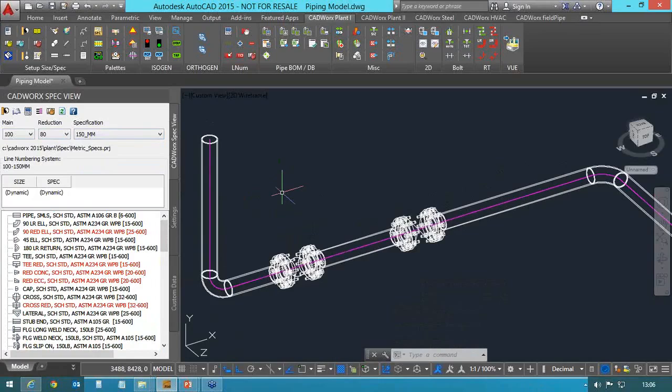Once you select this to place, you have the options of using point distance, or the component distance, or pipe endpoint distance, or maybe you can choose one more option of placing it as your justification, that is insertion justification. So any one of the options you can choose for placing this.